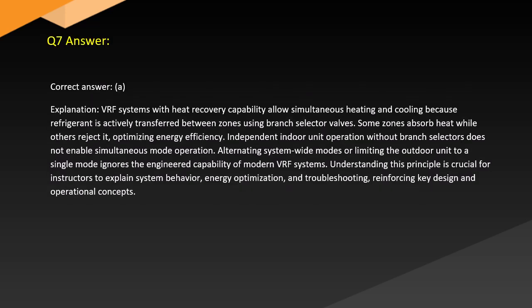Answer. Correct answer, A. Explanation. VRF systems with heat recovery capability allow simultaneous heating and cooling because refrigerant is actively transferred between zones using branch selector valves. Some zones absorb heat while others reject it, optimizing energy efficiency.